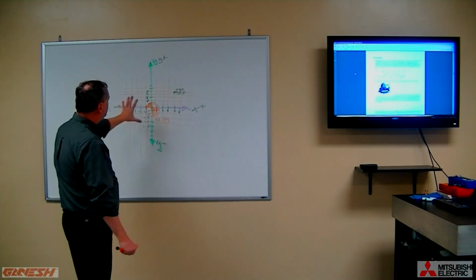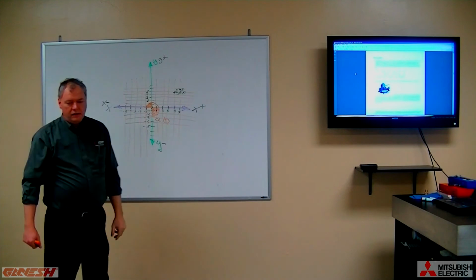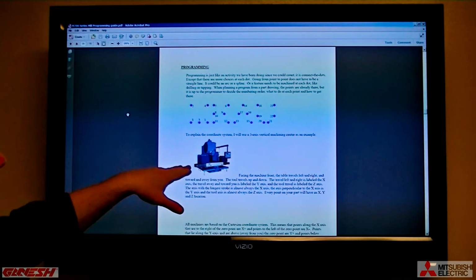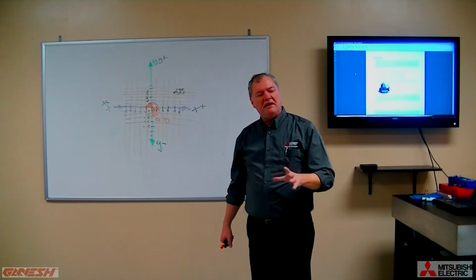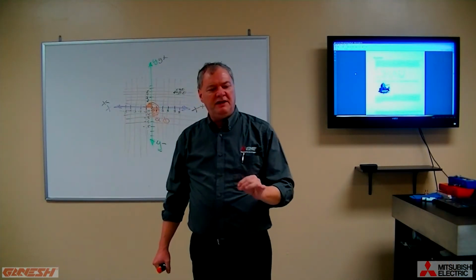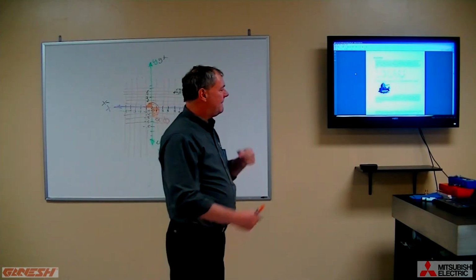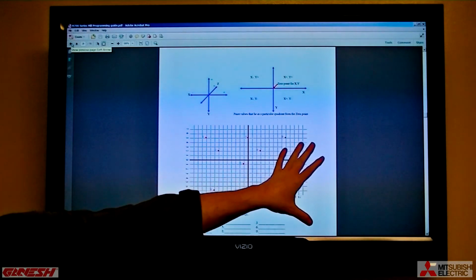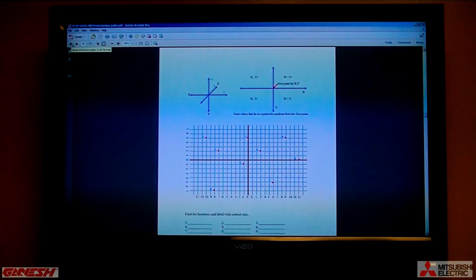So we can now position a part anywhere on this grid for our consideration. So if you look up here, we have the table, the head, and really our NC programming is just an exercise, believe it or not. You can boil it down to as simple as thinking of it as a series of connect the dots. And that's all it is. Let's go on and expand on that a little bit. If you look at this grid from your workbook, you'll see the thick dark lines represent the axes of x and the axes of y.